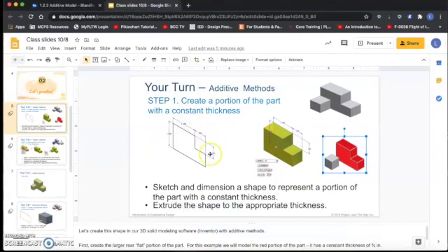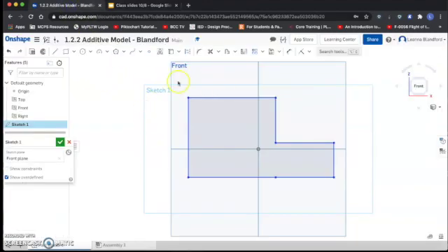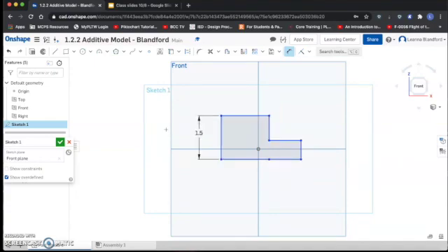And now I'm going to look back at this image. So I have some dimensions on here that I have to add so that this object is the overall right size. So let's start with this one over here. That is 1.5, and we're going to assume that it's in inches. So now I'm going to grab my dimension tool, and I'm going to click on the line and drag away. You'll see this number appears. And right now it's 2.73 inches. So I'm just going to type 1.5 on my keyboard and push the Enter key. And now resize my object so that line is 1.5.